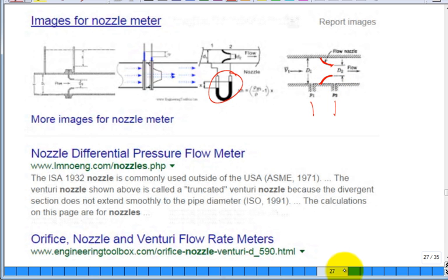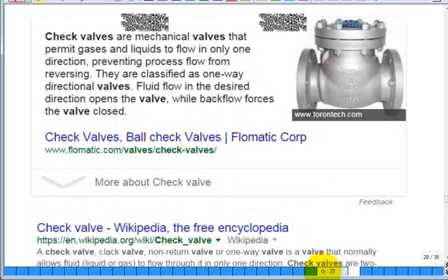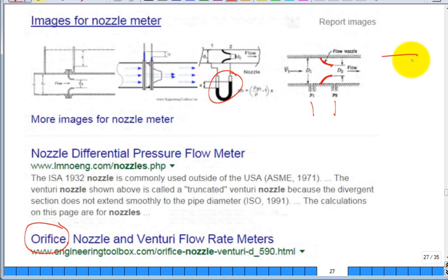And then also, I don't think I show it, but you have an orifice plate. The orifice plate's going to be easier to install, cheaper and everything, but it'll have even more of a delta P, more significant pressure drop. You'll have to pay more in pumping costs just to make that measurement continuously. But it's the same thing. Measure the delta P across the orifice plate.